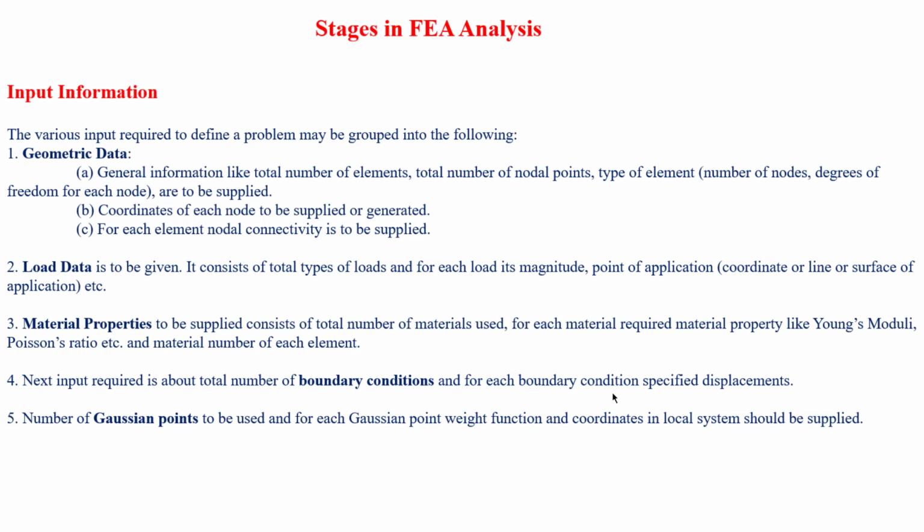When it comes to loading data, what all things do we need to define there? So we need to define the loading conditions like the pressure or the force which we are going to apply, what magnitude we are going to apply, whether it is on a surface or a point. So these things we need to define in the loading data. Next thing, the material properties. So which material we are going to assign, right? So the material properties for the static analysis, what all we need to define, and for the nonlinear analysis, what all things we need to take into account, what all the failure theories we need to take into account, right? So like Young's modulus, Poisson's ratio for the static analysis, isn't it?